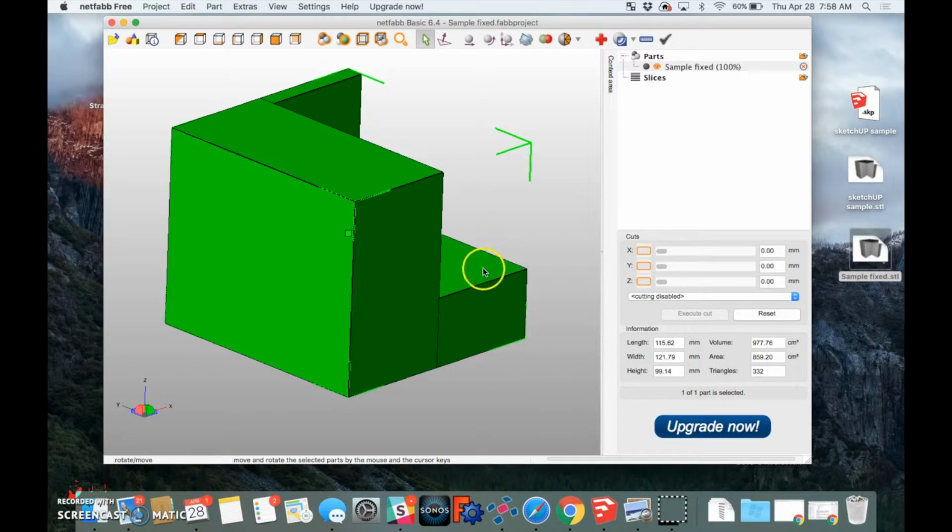Now if you're looking to scale it smaller, the key is to make sure that the wall thickness doesn't get too thin. So on average, you don't want the walls to get thinner than 1 millimeter. Now this will depend a little bit on the material and then the support and the design, but those are kind of good basic overarching guidelines.